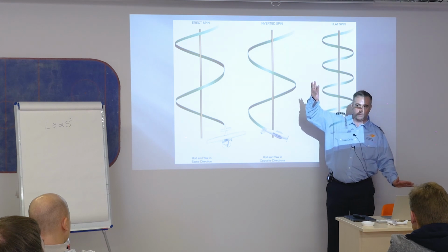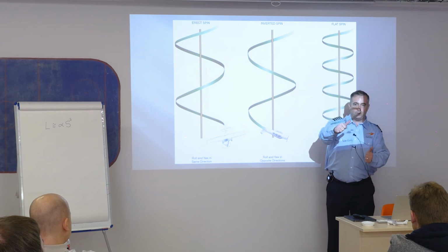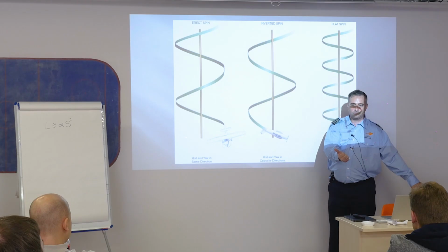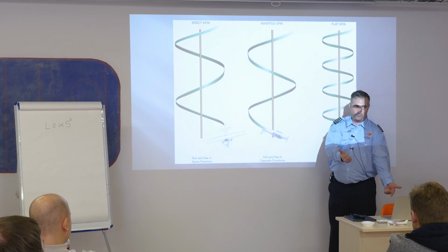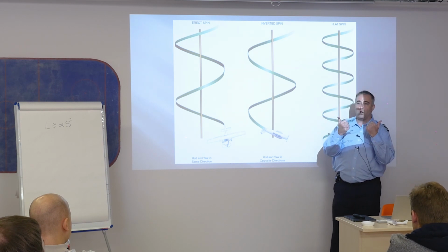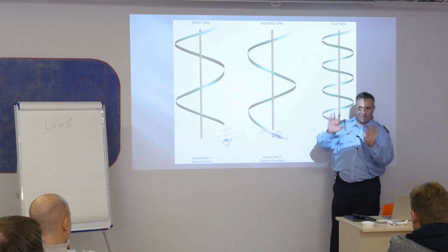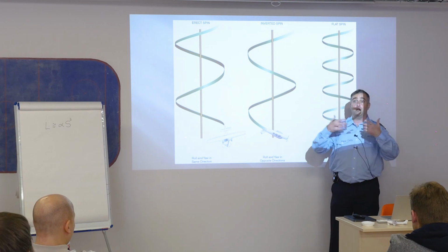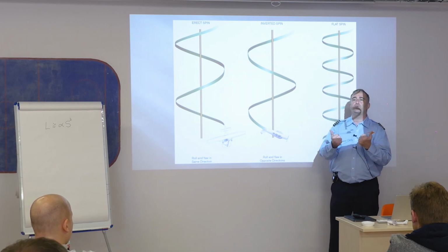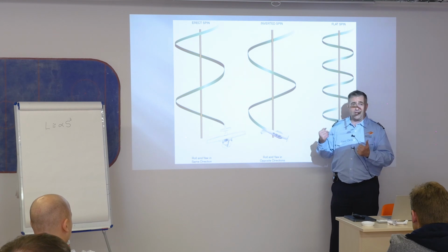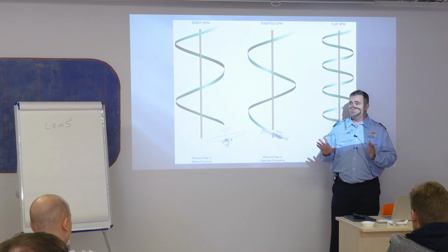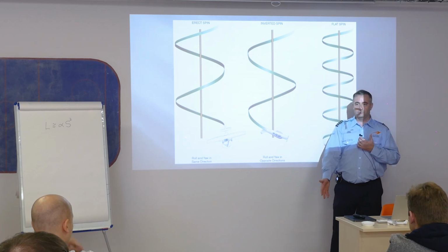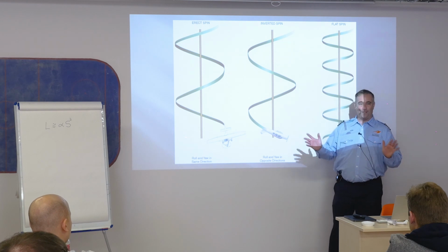It's stalled worse. Okay? If I attempt to recover, what have I done with that left aileron? I've made it worse. So during the stall, if I have any kind of upset left or right, maybe some recovery with rudder is called for, but not until I'm flying. I don't want to use ailerons. Keep them neutral. So power comes to idle, neutralize my controls, and then apply rudder in the opposite direction. I promise you the airplane will fly again.